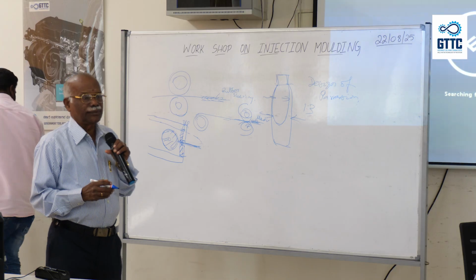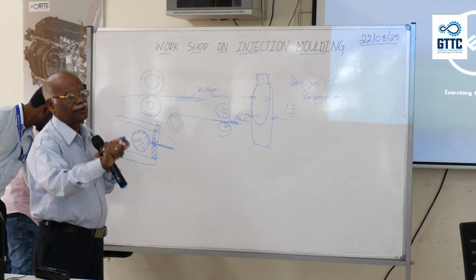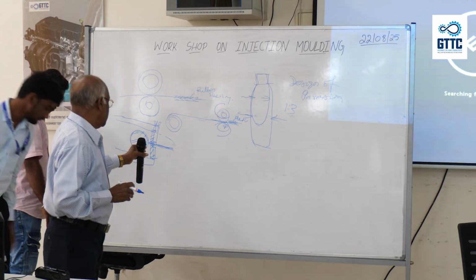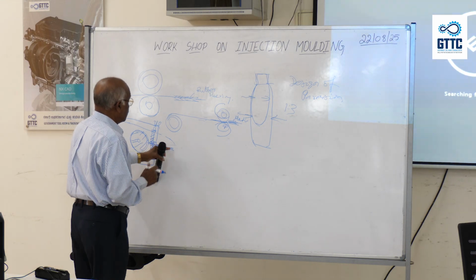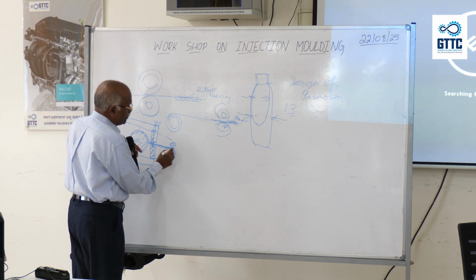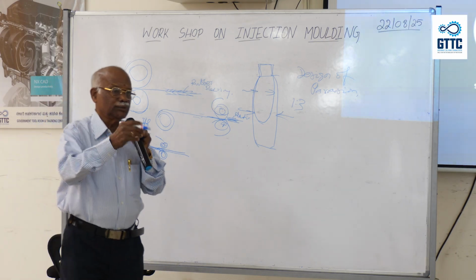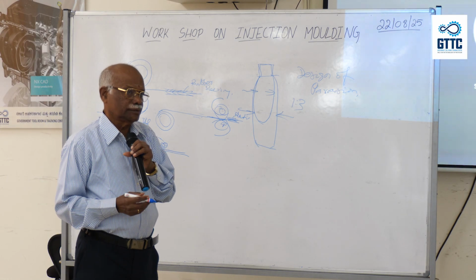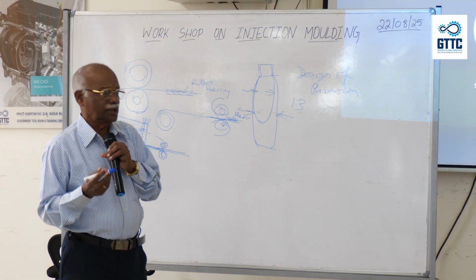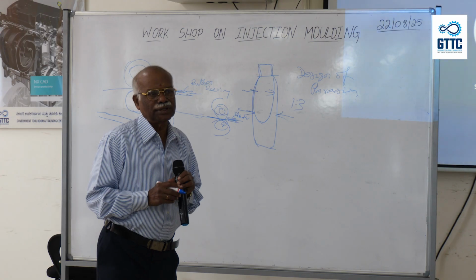Behind the cylinder barrel, the die plate will be fixed. Through that the plastic will be melted and coated onto the wire. There will be cooling. Once it comes out, there are a lot of cooling barrels which cool it and the wire comes out from there. This is a simple representation; I am not able to give you the complete picture, but it is the basic principle.